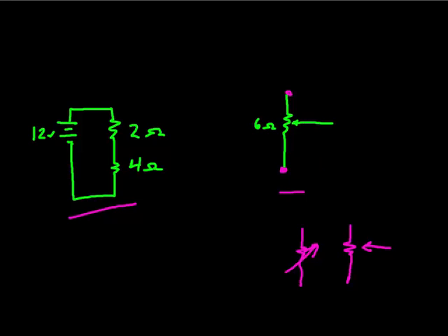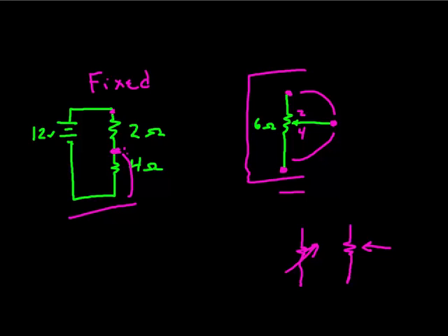If you've got this potentiometer knob turned to the point that there's 2 ohms of resistance at the top and 4 ohms of resistance at the bottom, and then this is really your node here in the middle, it's the same as measuring from here to here, would be the same as measuring here to here, right, across this point. Measuring here to here would be the same as measuring across here. The only difference between this potentiometer here and this circuit is that this is fixed. We'll use this word a lot as we go forward. Fixed, as in fixed bias or fixed load. You can't really vary these. To vary this, you'd have to pull this resistor out and put a different one in. In this case, you can actually vary it, but as you vary it and make this one go up, this one goes down proportionately, and vice versa. I hope you grasp this concept because we're going to use it here in just a second.